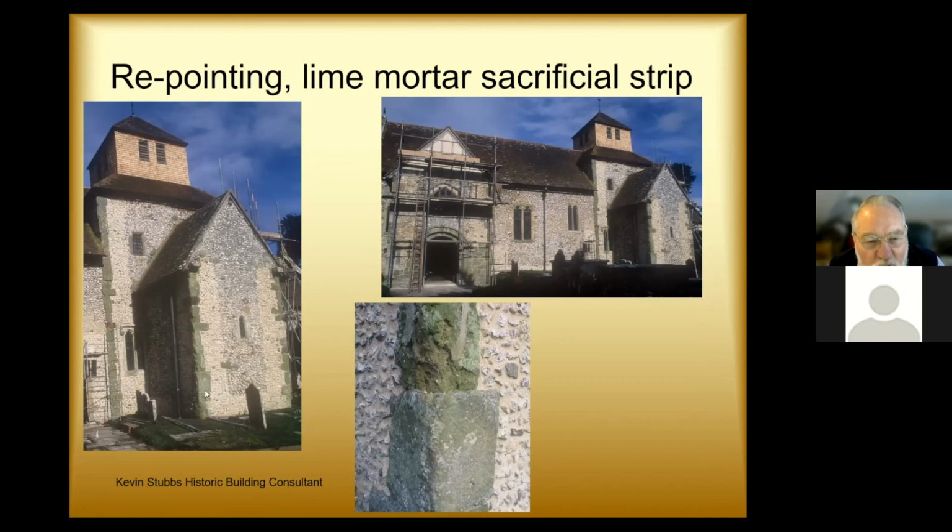They stripped it all back to show the glory of the original constructional material, and really to emphasize the flints, they raked out the lime mortar from between the joints, and they put back basically a one-to-one mix of Portland cement and boiler slag to give you a nice black pointing.